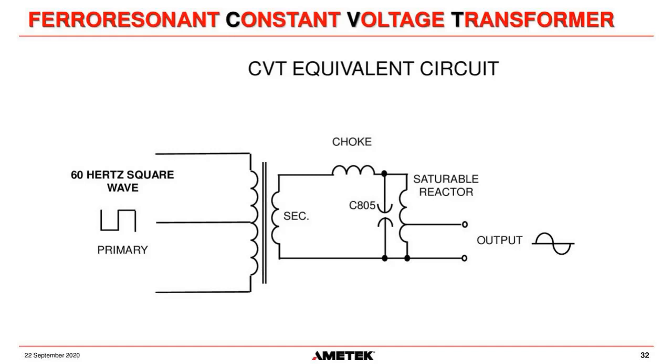Another nice thing inherent in this transformer is it is what we call current limited, and you can drop a crowbar right across the output of the transformer and it doesn't blow fuses or shut down or anything like that. The output voltage just goes to zero, and it'll sit there and run at about 150% of its rating into a dead short. So one application we see for this transformer is in battery chargers, a simple battery charger. We set the output voltage we need, the AC voltage, rectify that to DC, but it's also current limited, so we can have a large battery with a small charger, and we can't overload the charger with this ferroresonant design. So that's another advantage of this type of transformer.